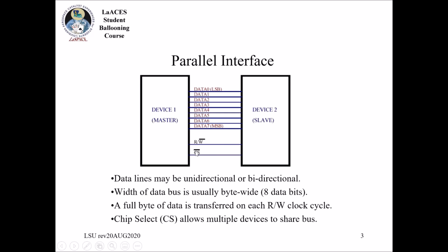Whoever made this presentation has a line above these labels. Whenever you see that, that's usually inverted logic. Normally, think of turning a light switch on, where you supply power to something. But with inverted logic, in order to get whatever we're working with to turn on, it actually needs the opposite: a ground rather than power.